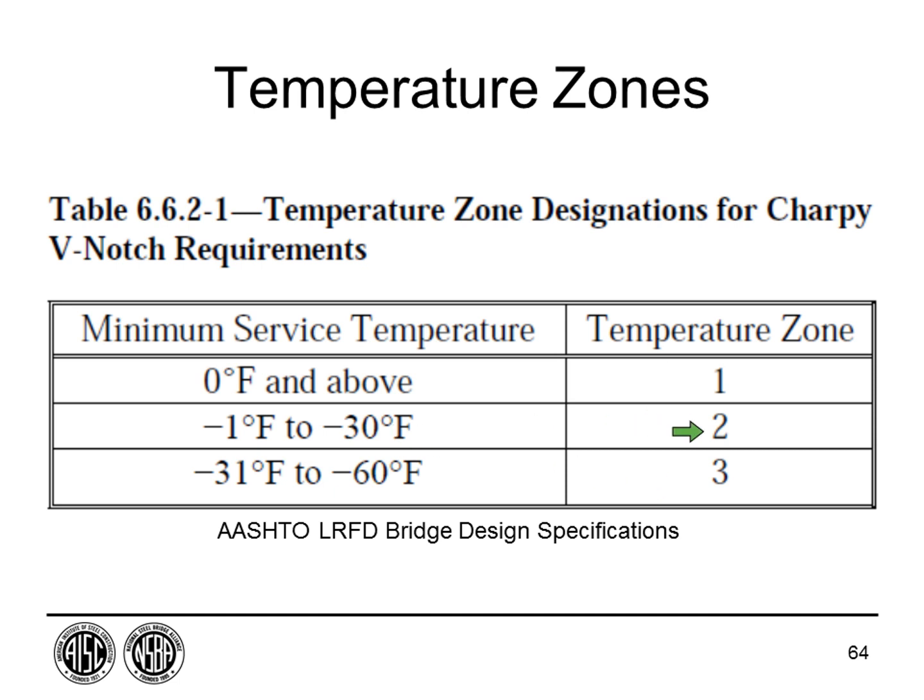Historically, we started with just zone 2, but the first bridge meeting we had was in Texas, and the Texas guys said it never got down to minus 30. And so that led to zone 1. And the chairman of the bridge committee was from Alaska, and he said it gets a lot colder, so that's how we got zone 3. So we ended up with those. Most of the country is covered by zone 2, and some along the coast and warmer areas would be zone 1. And when you get up to the northern part of the United States and Alaska, you may be in zone 3.